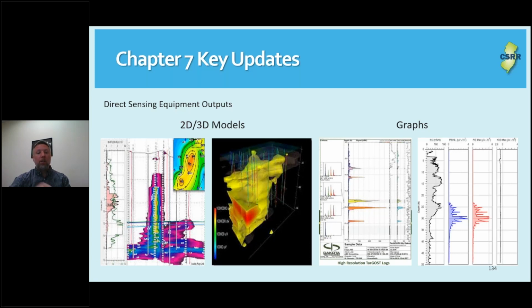One of the things that's beneficial about doing these profiling type tools is the fact that you can add multiple different sensors with these pieces of equipment to target specific compounds and then generate a specific output. Such as with MIP, you can add in a hydraulic profiling tool, which can provide you with hydraulic conductivity. You can do halogen-specific detectors, which is an XSD, and that specifically targets halogenated compounds like chloroform.